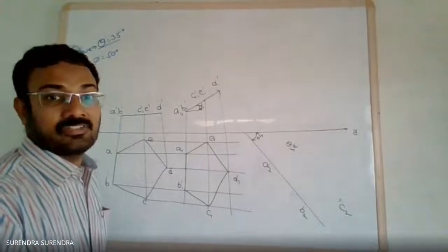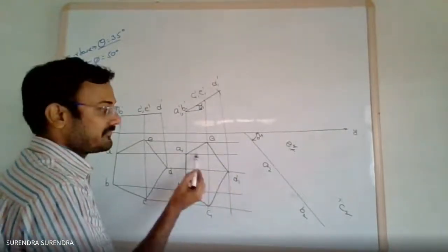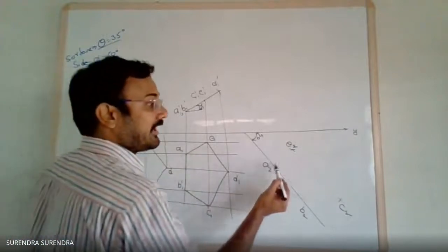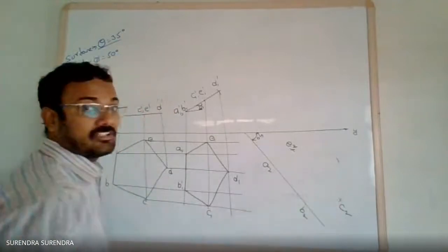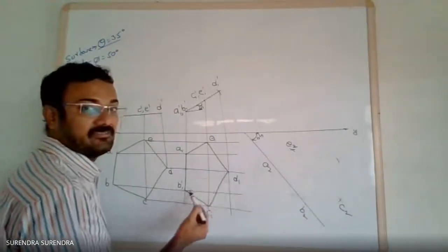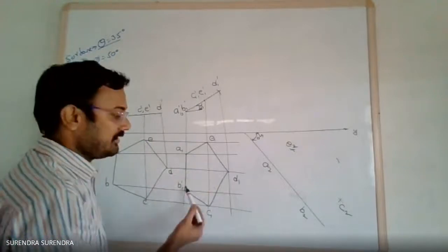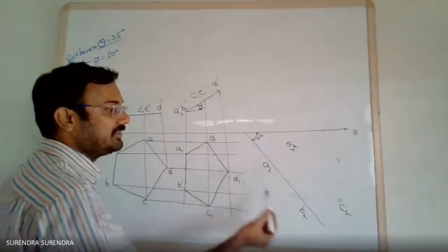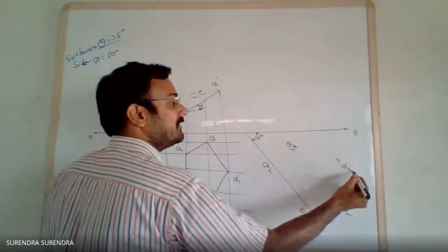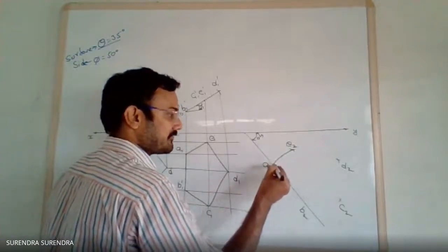Similarly, with the compass, measure the distance from A to D. With A as center, draw an arc. Always take AB as the fixed reference points. Measure the distance from B to D. With B as center, draw an arc. We get the point D2. Now join all of these with straight lines.